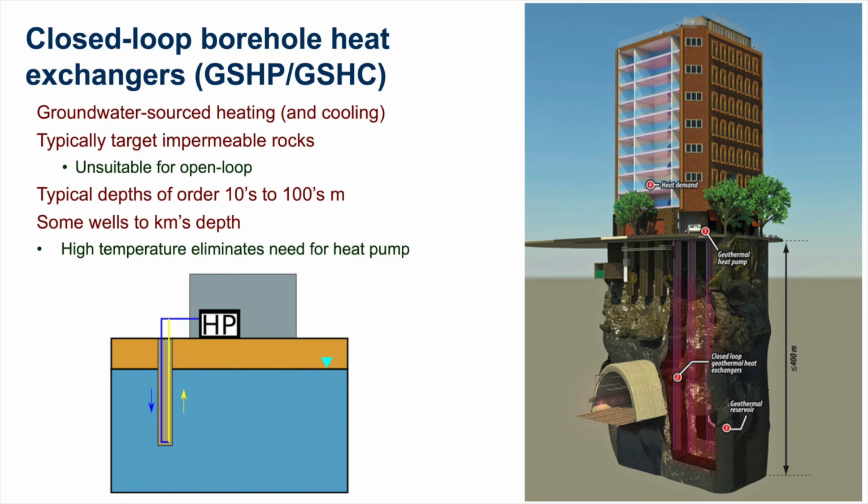So in London, for example, if you're happy to go below about 80 metres, you get into the chalk, a fantastic aquifer. But if you're not willing to drill deep enough, you've got a huge interval. We've got this 80 metres of London clay, which is impermeable, but you can still exploit that using closed loop boreholes.